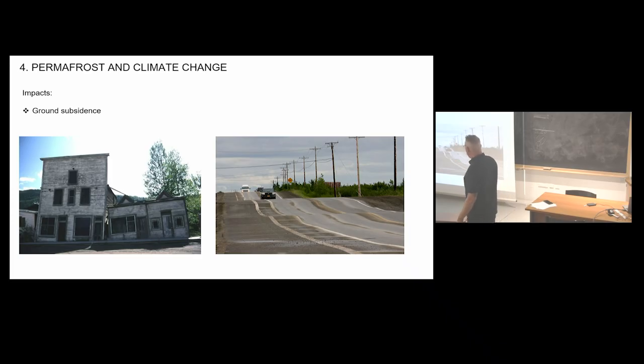So this was built over ice wedges. And then you change, and then we put asphalt. Big mistake. As a rule of thumb, no asphalt below the Arctic Circle, otherwise you completely degrade your permafrost. So we build, and we like black asphalt that rolls well and so on. You know, we're North American, sorry. And it degraded the ice wedge, then you're stuck with a road like that. And this is a famous, iconic Dawson Gold Rush era picture where they built and they had no knowledge of permafrost, so it affects building.